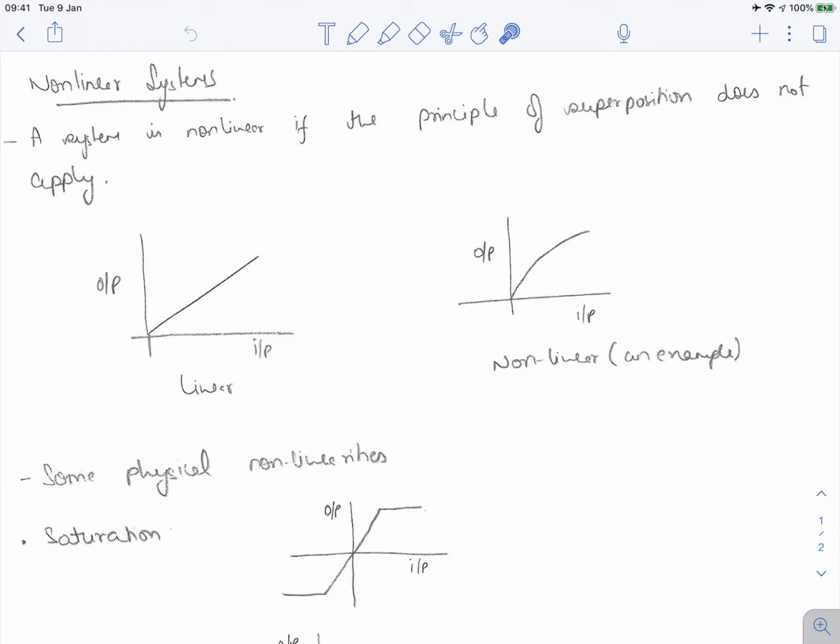Like I said, in this course we'll be studying mostly the transfer functions and their analysis. For a nonlinear system, you cannot obtain a Laplace transform or a transfer function. And so for a given nonlinear system, we will first linearize it to obtain a linear representation, either in the form of a transfer function or in the form of a state space representation, to do our further analysis.